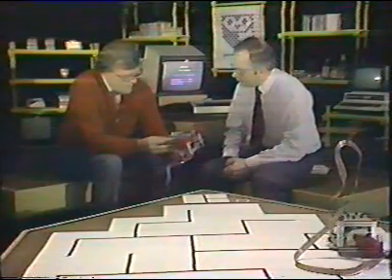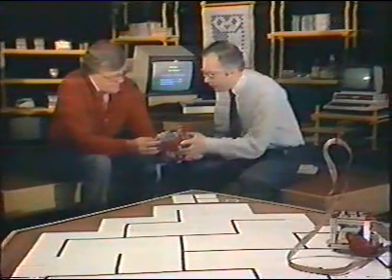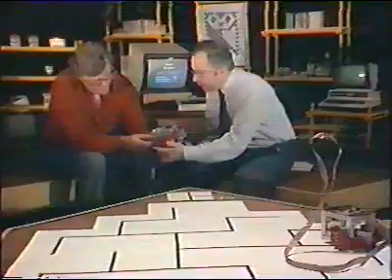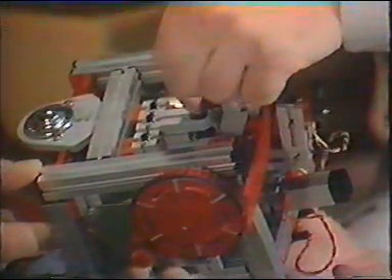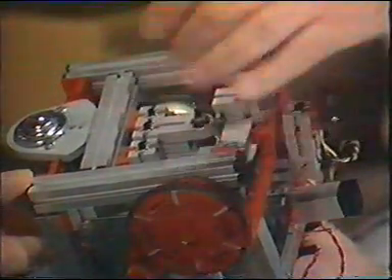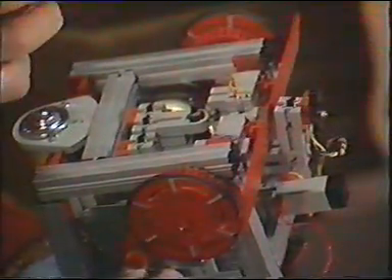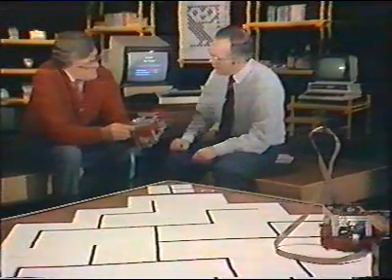Well, those are the input devices, and we've also got some output devices here. Right, well, we've got 2 output devices. There's a stepper motor here and a stepper motor over here, and as well as that, there's a device for moving the pen up and down. The stepper motor just moves it round 1 click at a time at about 7.5 degrees. When you give it 1 digital pulse, it moves, as you say, a very small angle.